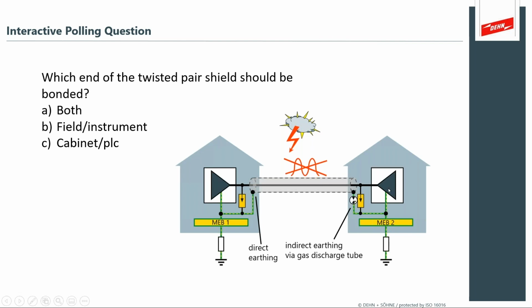The remote instrument needs to be protected because you have some valuable process, and the control cabinet end, what we call number 1 in this diagram, needs to be bonded and protected because you have, of course, that critical PLC device or that digital control system on this cabinet 1 end. And then lightning, your enemy that's trying to induce surge, either directly, indirectly, ground potential rise, anything it can, every way it can, it's trying to give you damage.